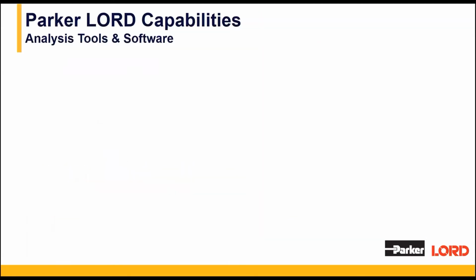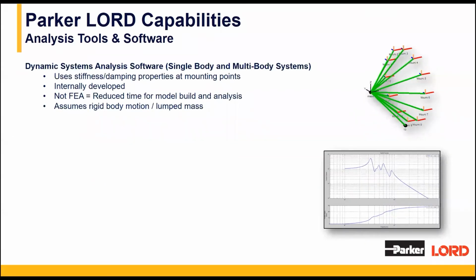We'll switch gears again. We're going to talk about some LORD capabilities. In terms of analysis tools and software, LORD has internally developed single-body and multi-body analysis software. It uses stiffness and damping properties at each mount point and is a non-FEA type system. It assumes rigid body motion and a lump mass. The reason we do this is to reduce turnaround time to analyze models. For dynamic motion, it's typically safe to assume rigid body motion and can get a quicker response in terms of estimating load and deflections of mounts and displacements of system.